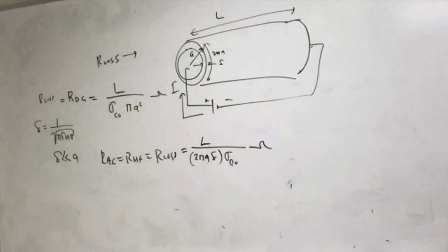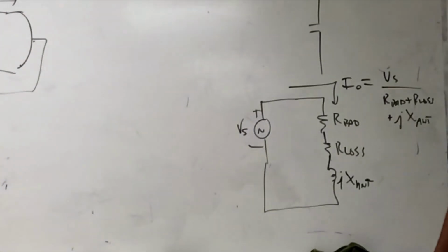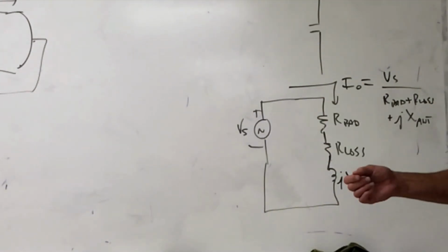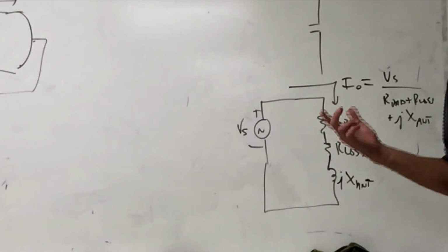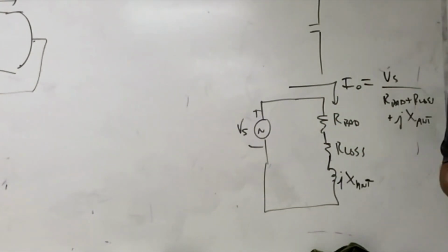I'm just telling you right here, that's not an easy one to just pull out. I can give you a formula for it, but to justify it you'd have to calculate the internal inductance, which we did for a short wire. Then you have to calculate the external, and that's a partial inductance formula. Do you remember talking about that? The partial inductance formula is a little nasty. It's hard to explain without going into great detail, and it's well beyond the scope of this class.